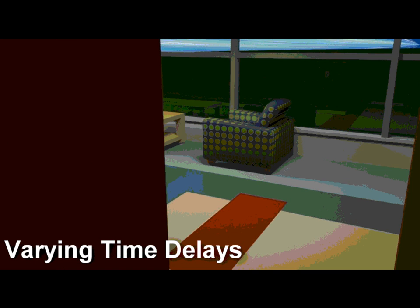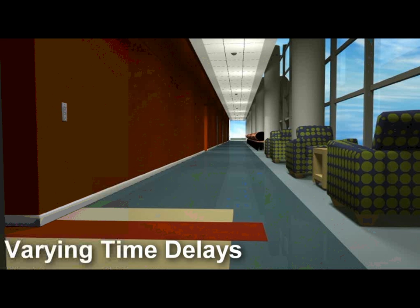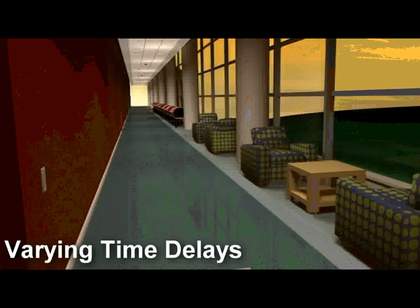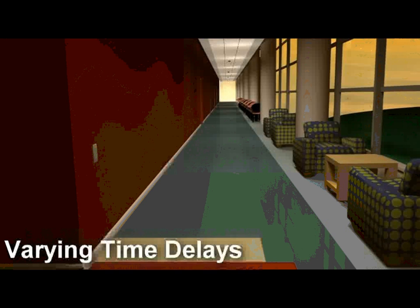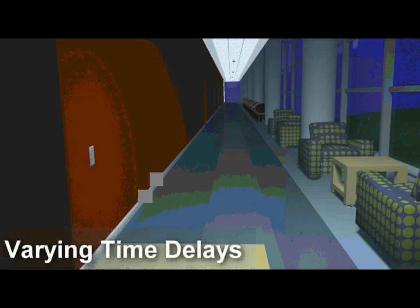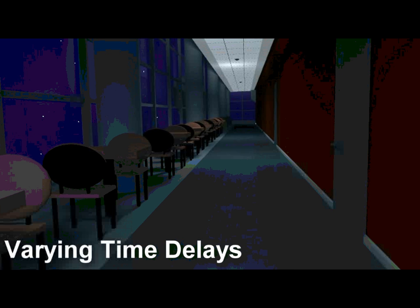Varying time delays. Varying the occupancy sensor time delays is a great way of picking up extra energy savings. For example, during the workday, the hallway lights may need to be override on, but during the early morning and evening hours, the occupancy sensors can be activated with 10-minute time delays. Later in the night, while the security guard does his overnight rounds, a 30-second time delay may be sufficient.